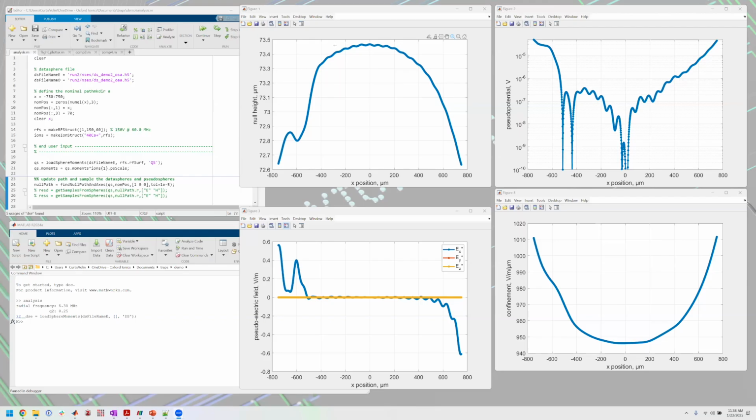So in the precision you'll get from those, you'll see features like this, but they won't be real features. What you're predominantly seeing there will be the imprint of the finite element mesh onto the results. So you'll see all kinds of wiggles and movement here, but it's simply the result of the fact that you get non-physical field at the mesh boundaries.